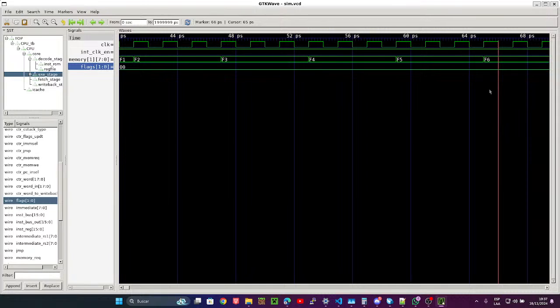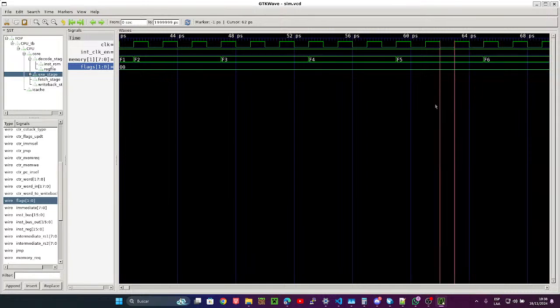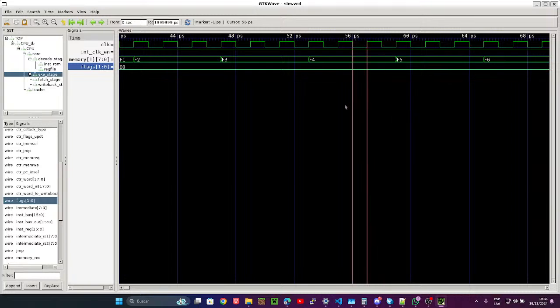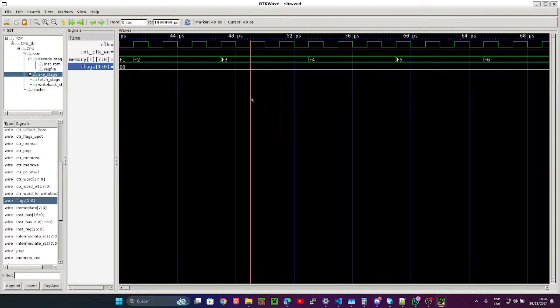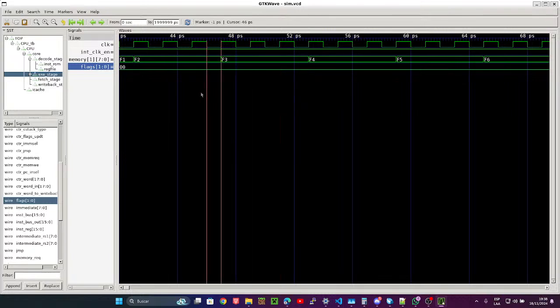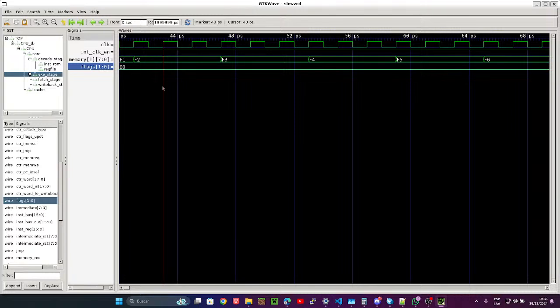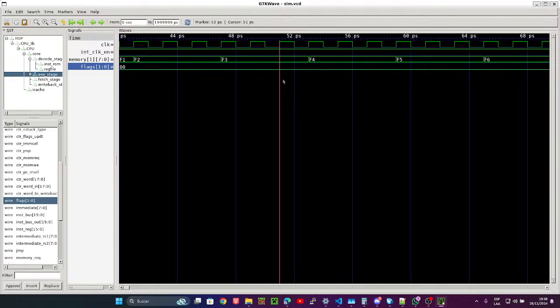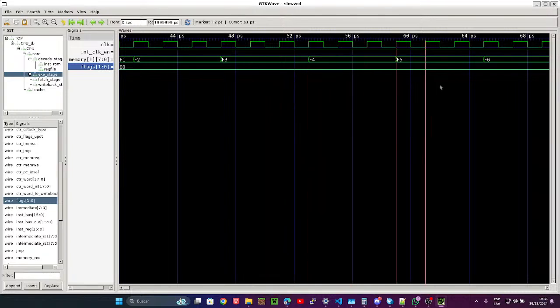If you find a chip like an LS series, 74LS something, and you leave its inputs unconnected, it's usually defaulting to 1, from what I've seen. But you are advised to always drive the inputs of CMOS chips, so 74HC series.